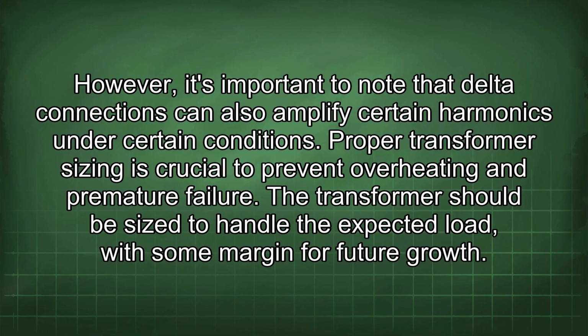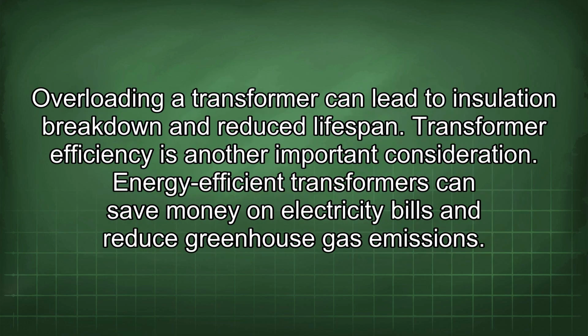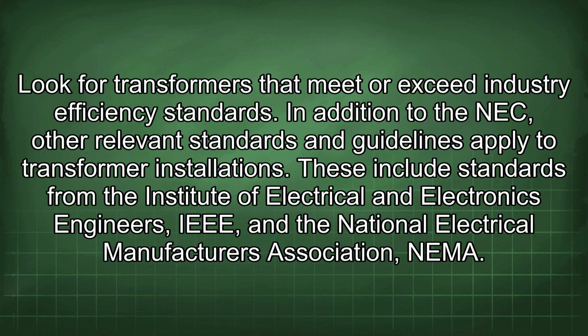Proper transformer sizing is crucial to prevent overheating and premature failure. The transformer should be sized to handle the expected load, with some margin for future growth. Overloading a transformer can lead to insulation breakdown and reduced lifespan. Transformer efficiency is another important consideration. Energy-efficient transformers can save money on electricity bills and reduce greenhouse gas emissions. Look for transformers that meet or exceed industry efficiency standards.